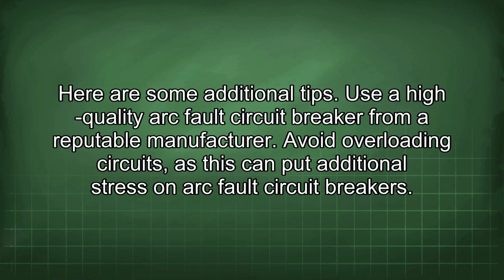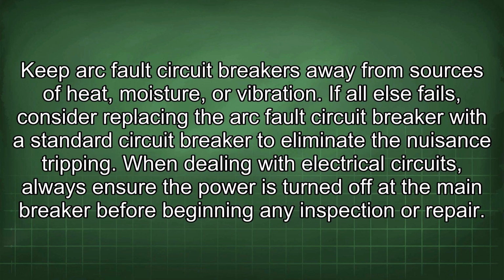Here are some additional tips. Use a high-quality arc fault circuit breaker from a reputable manufacturer. Avoid overloading circuits, as this can put additional stress on arc fault circuit breakers. Keep arc fault circuit breakers away from sources of heat, moisture, or vibration. If all else fails, consider replacing the arc fault circuit breaker with a standard circuit breaker to eliminate the nuisance